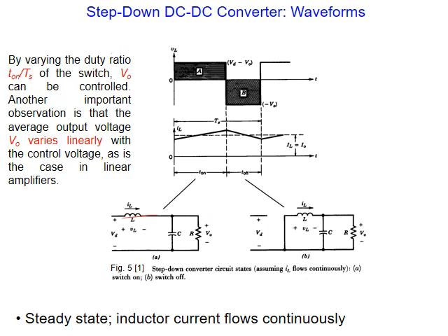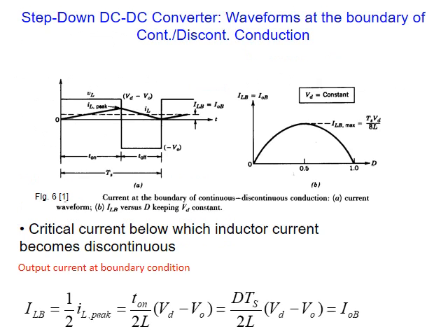Inductance current here is equal, we assume that the capacitor is open circuit, fully charged. This is DC. So current here is equal to the current here. Input current equal to the output current. Inductance current equal to the output current.